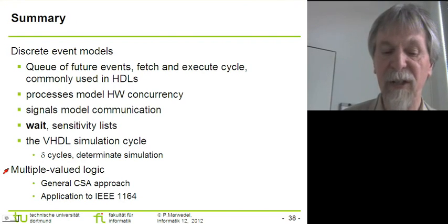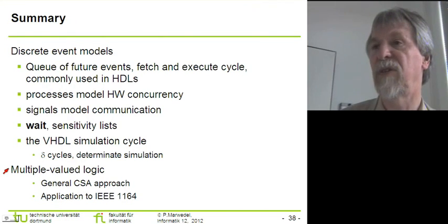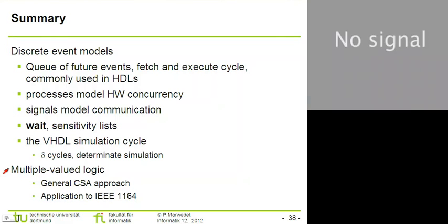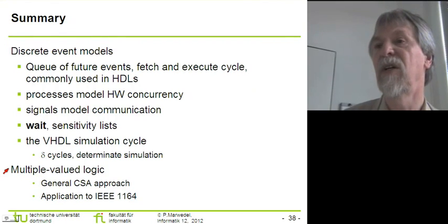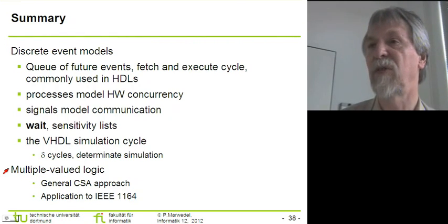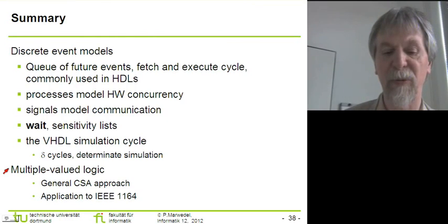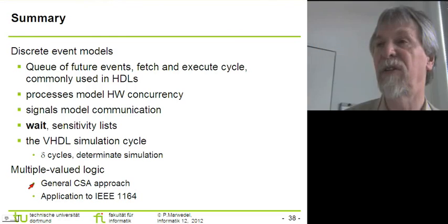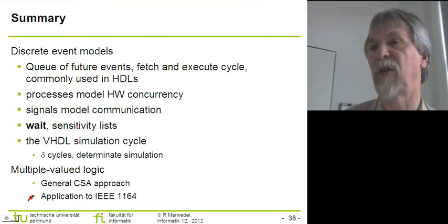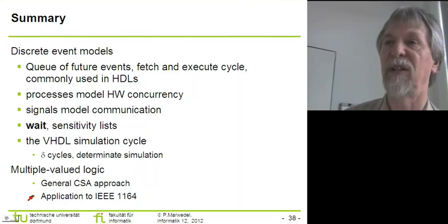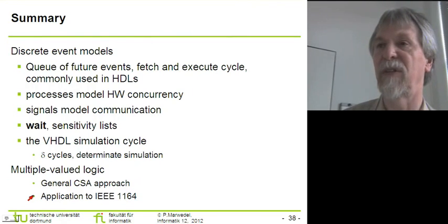And then during the last minutes, I introduced you to a special case of multiple valued logic. I introduced you to a way of creating value sets for multiple valued logic. We saw the general CSA approach, and then we saw that this can be applied to IEEE 1164, and we saw that without the background it's very difficult to understand IEEE 1164.